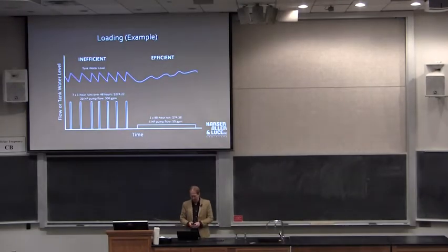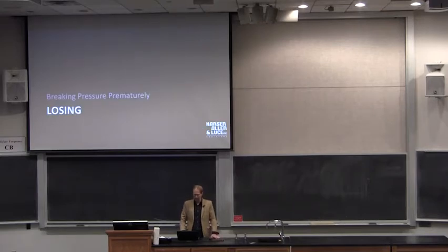So here's just a quick example of another real system where here they would use loading. The pumps would turn on, fill the tank, and it would cost them $274 a month. This is a very small pump, but $274 a month to do it this way. And after changing to a more sustainable way, removing the loading, their bill went down to $74. So we're using more of the storage tanks, and the source is feeding the system at a more constant rate.